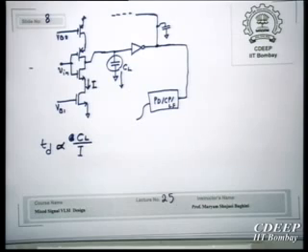Okay, so then you keep it as it is, and even if it takes time, see, ring oscillator oscillation doesn't take time, but when you keep it in the loop, it will take time. But it's okay. You have enough time. Keep it running overnight. This is usually what we do. But let's have some practical anyway. It may be required to design at this frequency. I mean, this frequency is a very typical frequency, 40 megahertz to 320 megahertz for a clock.